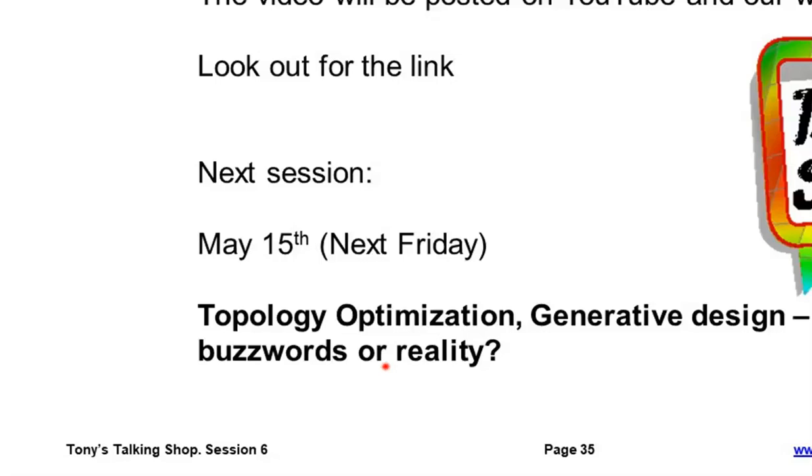We're based on a power law is the typical approach that we would take. That's the approach I've taken when I've written a MATLAB solution or an Excel spreadsheet solution. That's how we define our nonlinear, as you say, elastic plastic sigma epsilon relationship, so the nonlinear stress strain relationship. There's no reason why you shouldn't use instead test data, so that would be table data, or you could use a piecewise linear fit. So there are other forms that you could use to introduce that. I've used a power law.